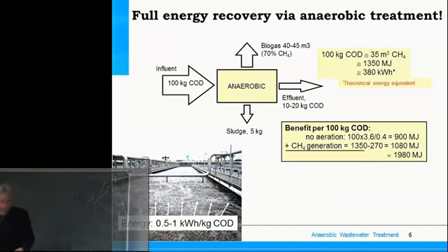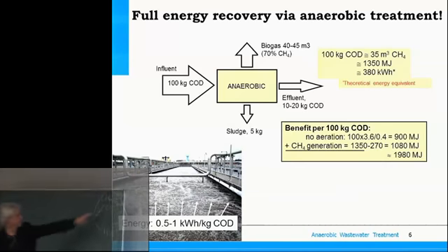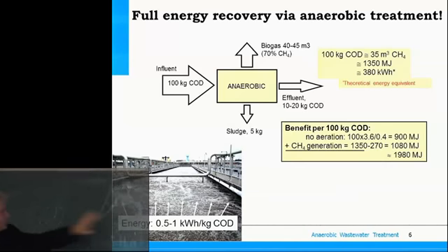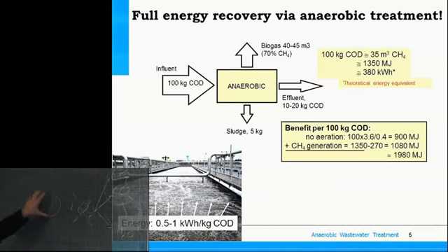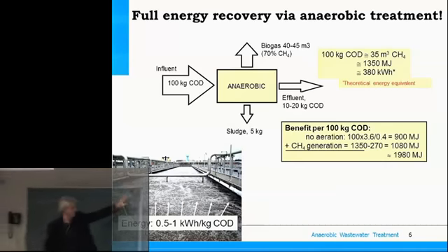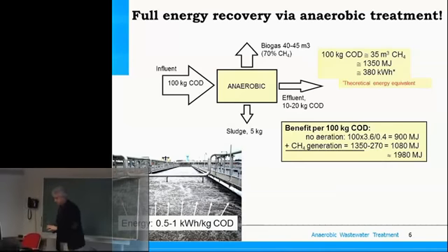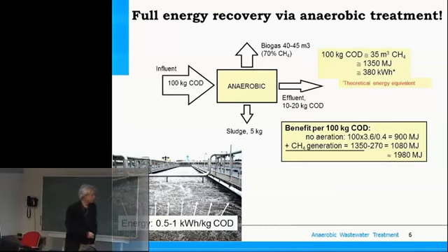And CO2. Well, this has the energy content, this has no energy content, so the organic matter energy content is channeled from the organic pollutants to the final end product, methane gas. Alright, so this means that there's a huge benefit on energy. Since we don't need aeration, there is no need for aeration. Meanwhile, we have the production of an energy-rich end product.